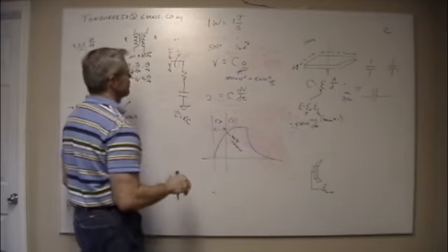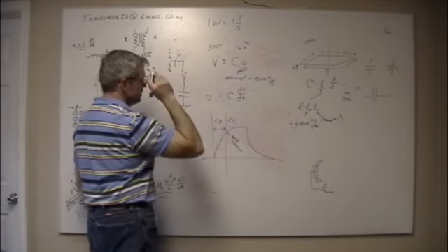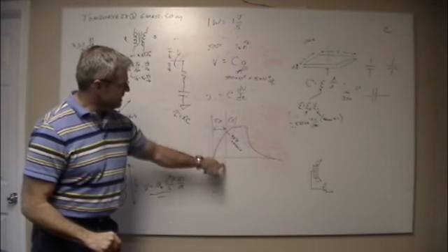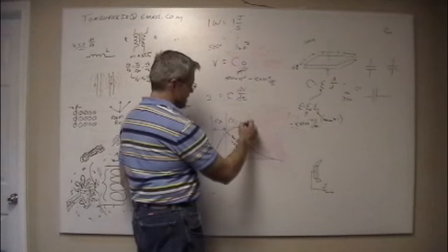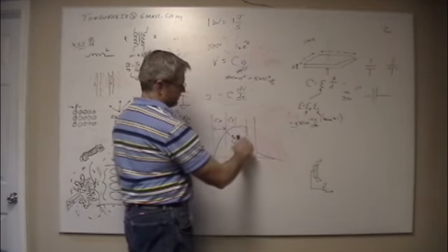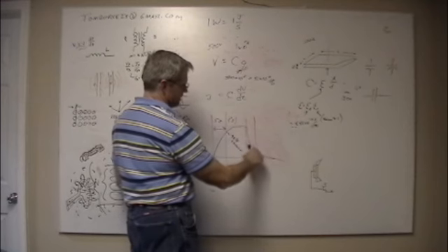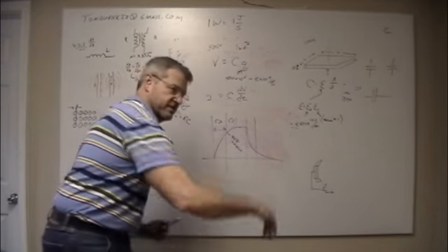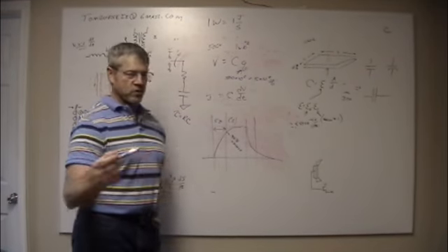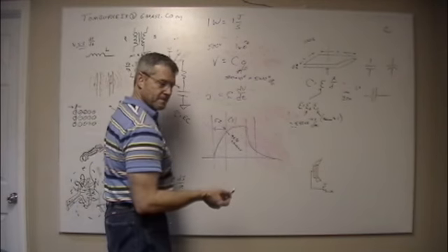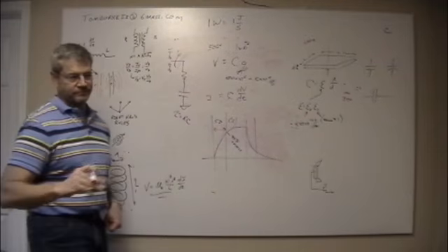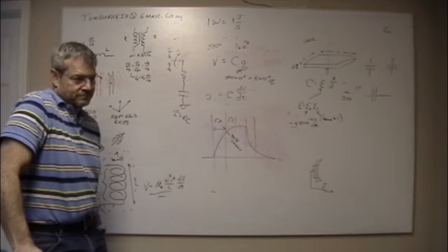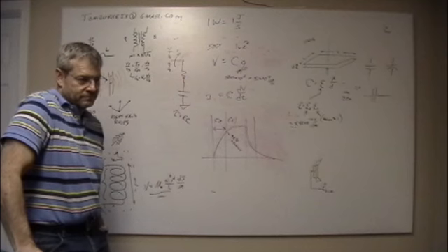So if I've got 1 microfarad over there, 98% charge, yeah, you can work it backwards, and you can come out with that and say this is basically how long, and this is not quite 5 tau, but it's pretty close. So you can say, well, it takes pretty quick to get to there, but you can work these backwards, right? You can say, oh, well, I've got this much charge on the capacitor, and this is the resistance of my circuit, and this is how long it's going to take to discharge, and that sets you up a time constant. You can actually start working on filters and things like this. Well, so on my NeoPixel strip, on the 5 volt supply, they recommend a 1,000 microfarad cap across it to stop the spikes from damaging the NeoPixel strip.